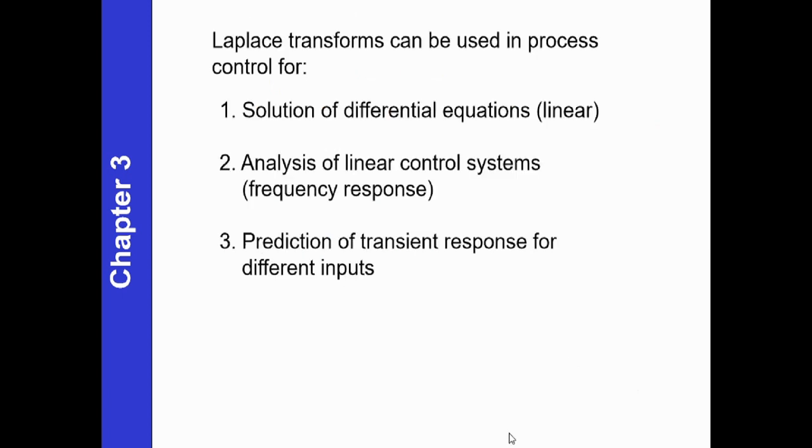So in short, we can say that Laplace transforms can be used in process control for, one, solutions of differential equations, and those need to be linear differential equations. Two, analysis of linear control systems, there is a frequency response. So the question is, if it's non-linear, how to analyze? You also learn in maths that for non-linear, you can linearize it first, then solve it using Laplace transform. And third, predictions of transient response for different inputs.